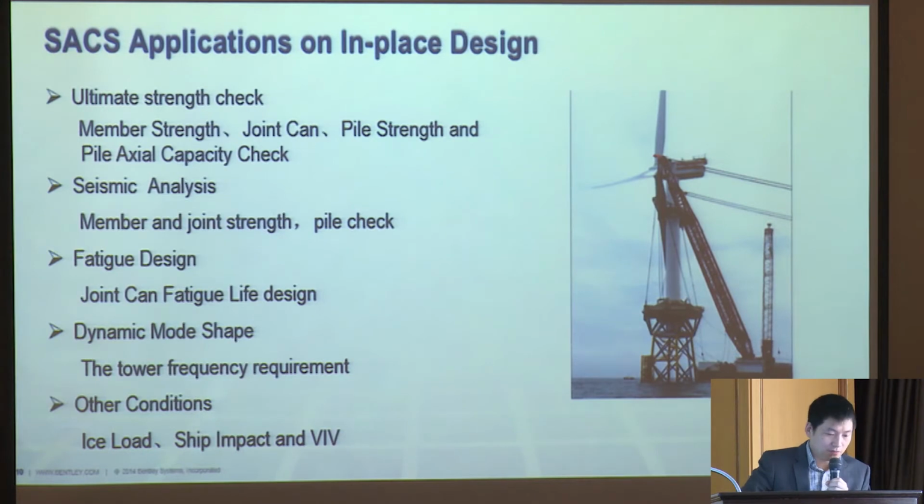For some platforms, there are some other design conditions like ice load design, resistance design, and accidental load design, or VIV. So sometimes you need to check the VIV, vortex-induced vibration, and you need the orbital particle velocity at different elevations, and SACS can calculate this automatically.